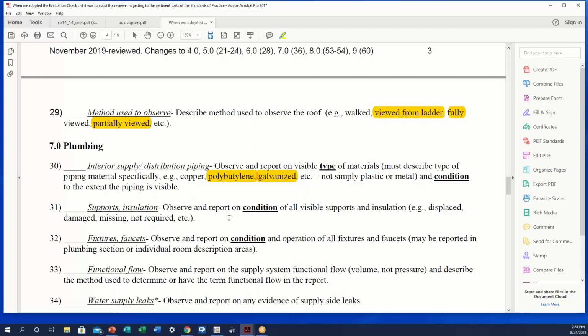So how many of you write up the whole ceiling? You're up there on your little ladder, you're trotting around, and you see the pipe sticking up out of the insulation, and it's running like a porpoise through the attic, and then it's exposed to the heat of the attic. Do you write that up, or do you just ignore that? Well, now you won't ignore it. But either way, you'll probably write that up and say the pipe is up out of the insulation. Have a plumber who's familiar with the insulation requirements of PEX consult with you as to your options.